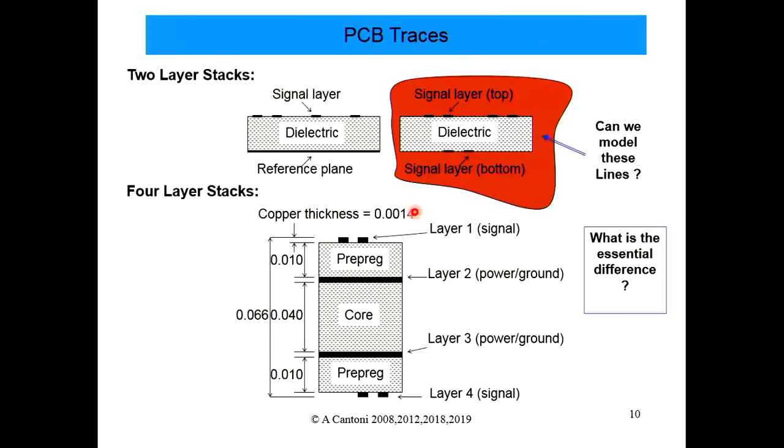Whereas here, it's not uniform, okay? So we can't develop a model for it, it would be very difficult, okay, for each line. So those sorts of circuit boards are only good if the signals are very slow, okay? Have slow rise and fall times, and then the wires look like perfect wires, okay? They don't have to be considered as transmission lines, okay?